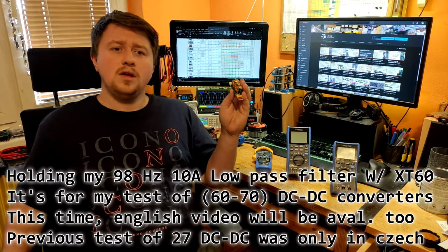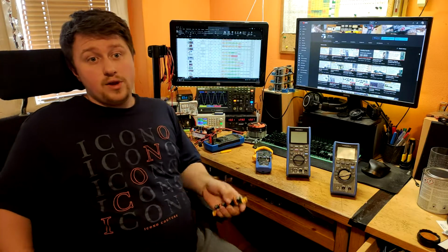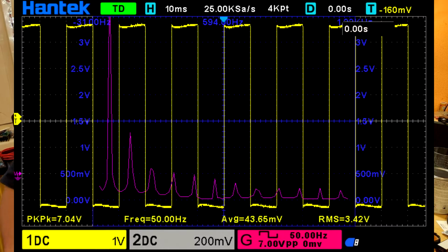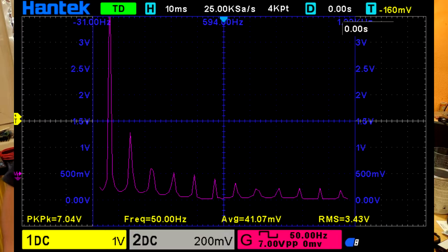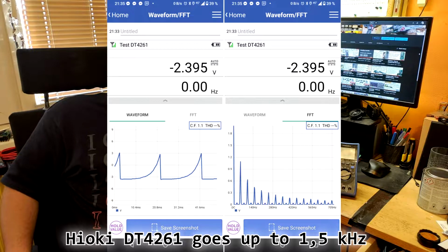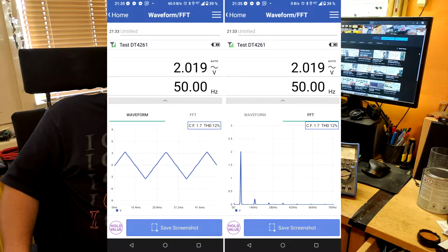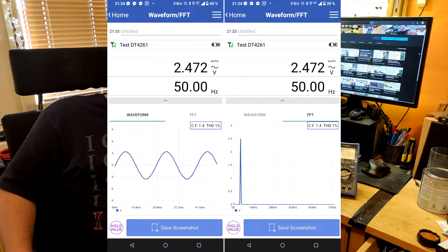Why so? Any properties of any components like chokes or capacitors refer to harmonic frequencies, sine frequencies. If we don't know how our component will behave with a function different from harmonic, we must decompose the function into harmonic parts. This is done by FFT. Any signal can be decomposed to harmonics. Any. We can then isolate the separate harmonics and determine how well each of them behaves in this component.